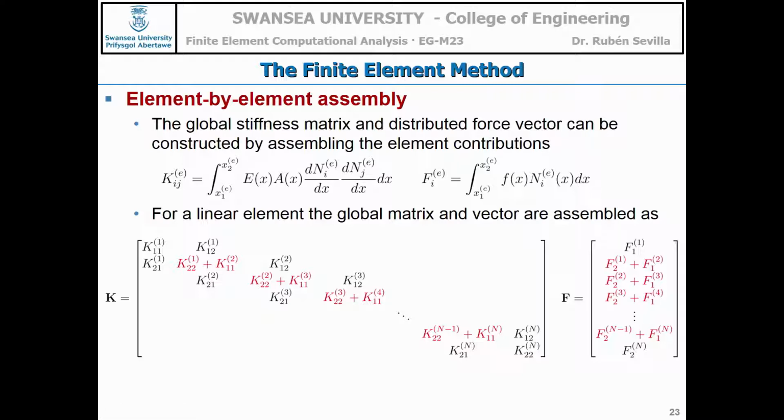And now what we do from a practical point of view is, in order to build your stiffness matrix, you're going to compute integrals in an element only. Look, I'm changing something slightly here. This is Kij, so this is the term ij of your matrix, but with a superindex E. That means I am integrating in one element only.